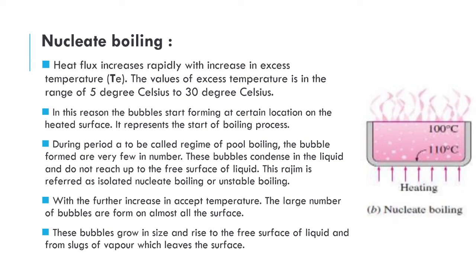With the further increase in excess temperature, a large number of bubbles are formed on almost all of the surface. These bubbles grow in size and rise to the free surface of the liquid and form slugs of vapor which leave the surface.